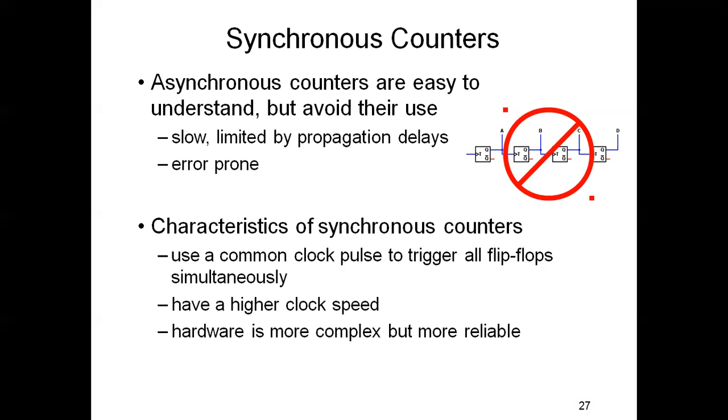Counters are the widest application of flip-flops. A counter is a group of flip-flops with a clock signal applied. Counters count the number of clock pulses. Hence, with some modifications it can be used for measuring frequency or time period. There are mainly two types of counter, asynchronous and synchronous counter. In the previous video we learned the asynchronous ripple counter.